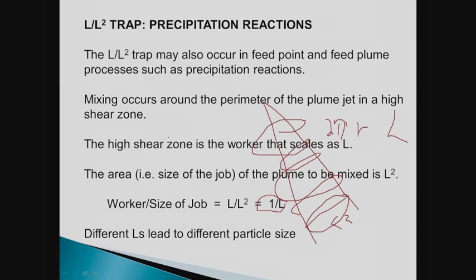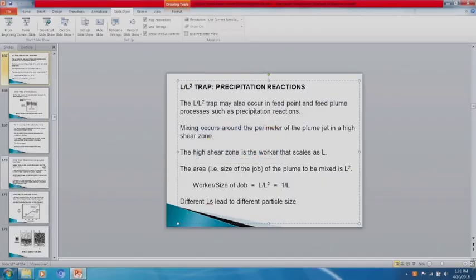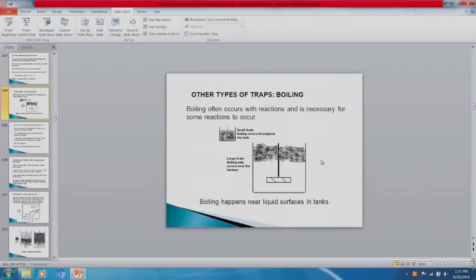Anyway, moving right along here, and let's try going back. We'll end the show and discard. So this is a very famous scale-up, a large chemical company. We won't say who. Small scale, they had a boiling reactor. Large scale, they had something looking like this. So this is 30 feet here. So the top portion of the reactor was boiling, and the bottom portions of the reactor, due to the hydrostatic head, was not boiling.